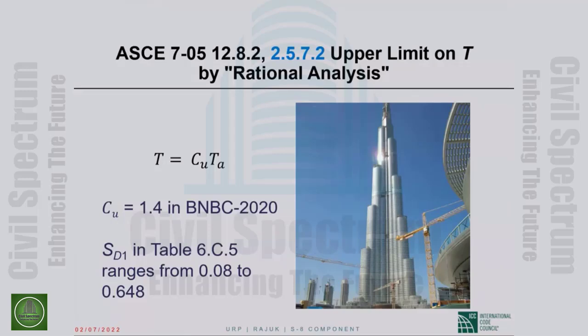Even when you do dynamic analysis, the results of dynamic analysis have to be scaled to the results of the static analysis, either 100% or some percentage. But the dynamic analysis is tied to static analysis, and static analysis is dependent on this approximate period. Even when you do rational period computation, you do not get away from that. The only time you are independent of this approximate period is when you are doing nonlinear time history analysis. Then you are not tied back, but that's the only case.